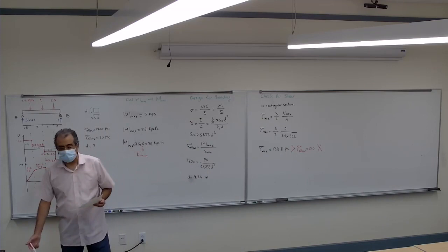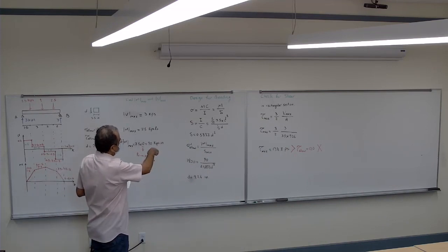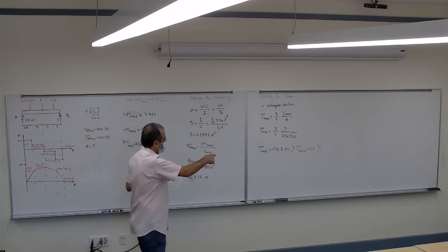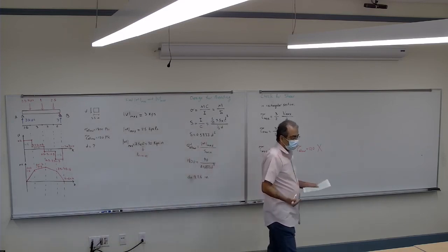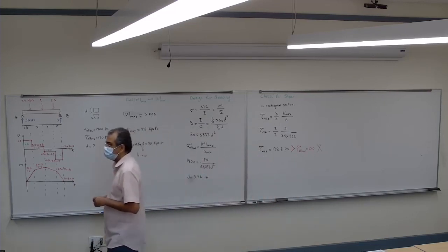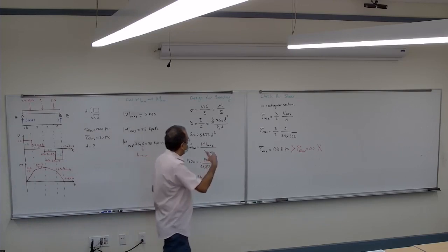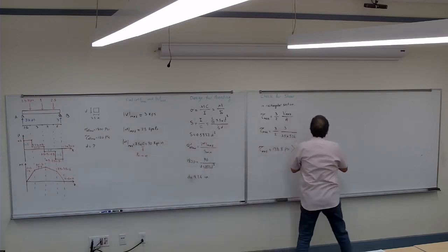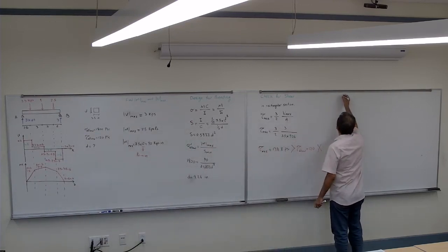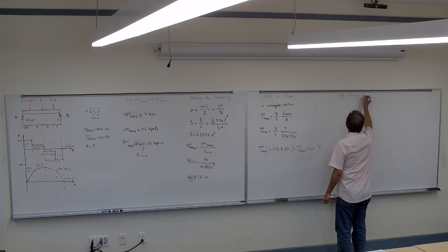So now that I know it's failing under shear, if I design it for the bending, it's going to fail under shear, I have to go ahead and redesign it. So I have to redesign it for shear.